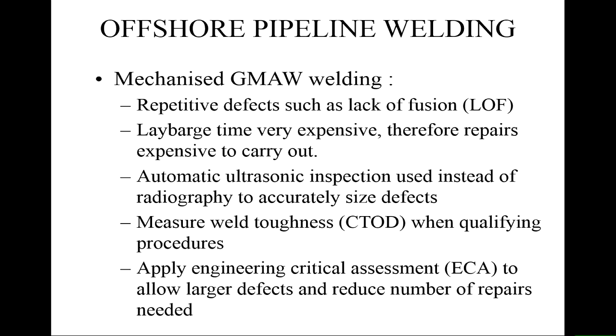So we basically do extra work offshore because we can't afford to get it wrong. And we apply engineering critical assessment to decide whether we're going to allow the defects that we've got to exist or whether we actually have to repair them.